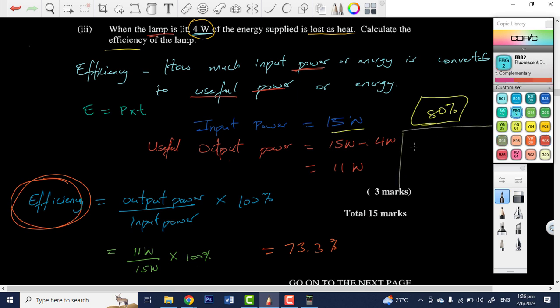So you have the efficiency as a percentage. Let me do it right here. See if I can squeeze it in. So this is 80%, right? The output power is what we're trying to find, so let us say this is P, output power. And we know the input power as 15. Remember that 80% as a fraction is simply 80 over 100. So we'll simply say 80 times 15 divided by 100, or for simplicity, we just multiply 15 by 0.8. And I think I get 7.5.